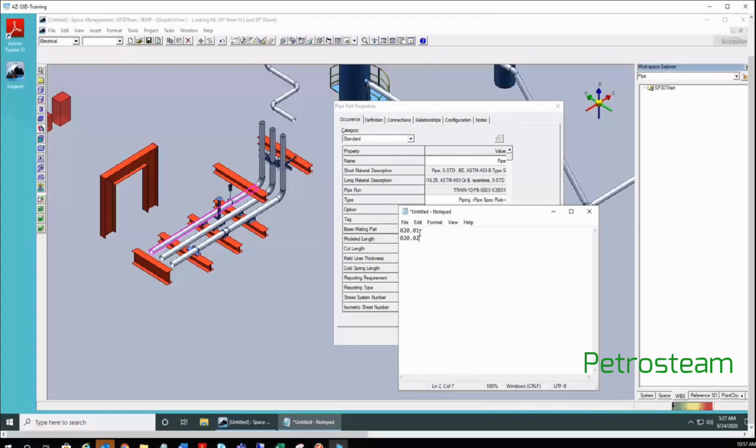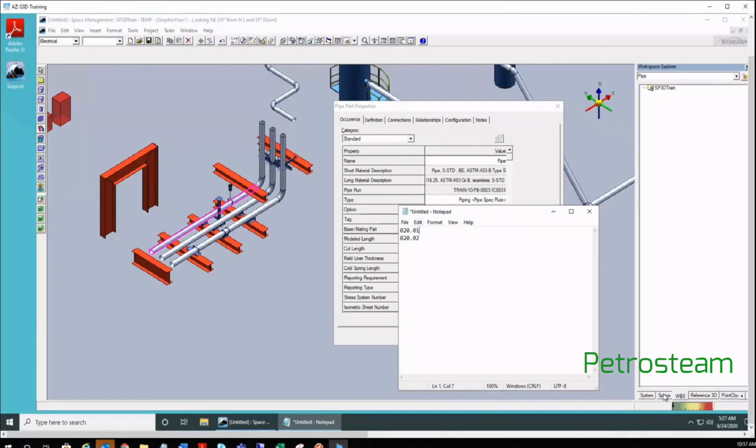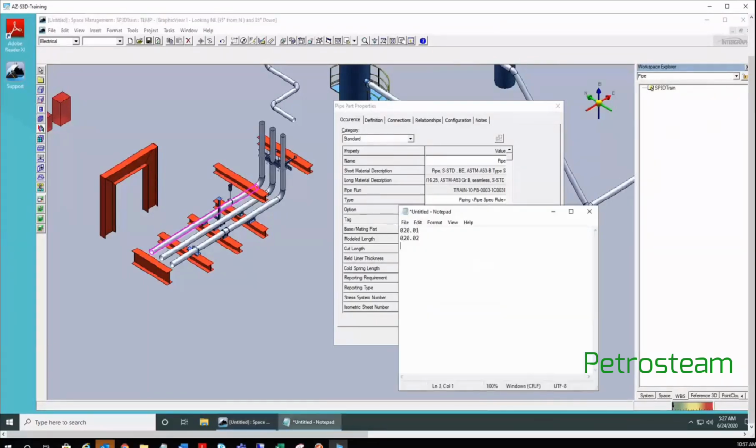There will be an additional property available within the project for parts. It will be volume, and volume will be assigned to 02001. After that, under the WBS tab, there will be a 02001 WBS item. Within that, one isometric will be created. For that also the naming will be, say right now the isometric name is TRAIN 10-P. Okay, that is your isometric name.